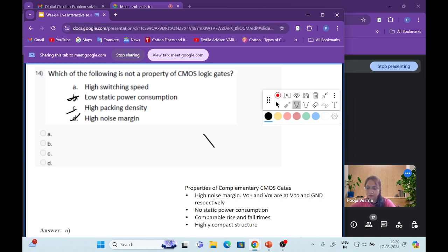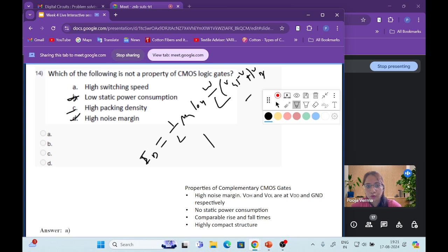And also there is a voltage current relationship in the MOS transistor in this form, right? We already know the voltage and current relationship for MOS. There is Cox, W by L, (VGS minus VT) into VDS minus VDS squared. This is the voltage current relationship of a MOS transistor, so that is applicable for both PMOS and NMOS.